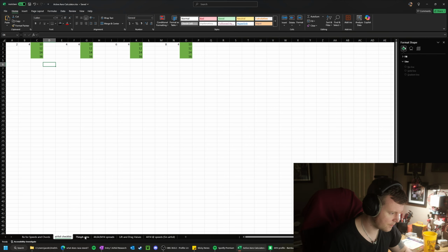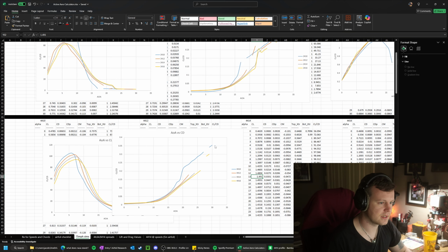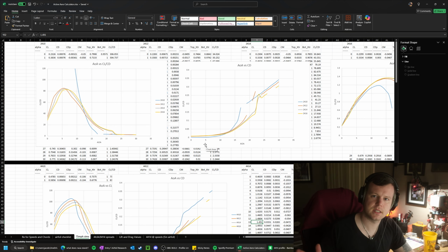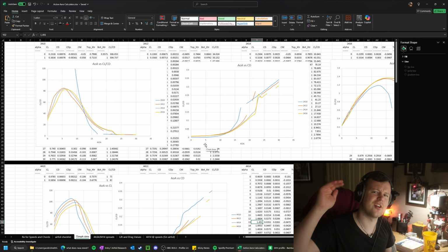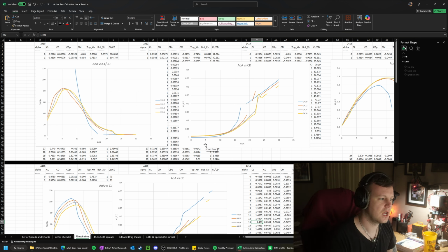So then I modeled them at 75 miles per hour. I decided 75 miles per hour because that seemed like the higher end of daily driving speeds, and I want this to be suitable to keep on your car for daily driving, and I wanted it to provide as little drag as possible at those higher speeds, because we're already dealing with a lower powered car, and I didn't want to sacrifice any more power than I needed to.